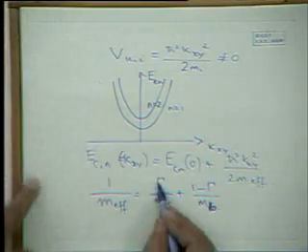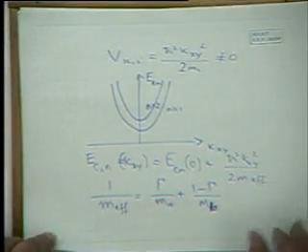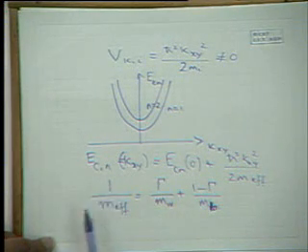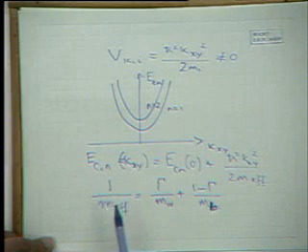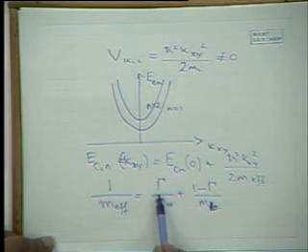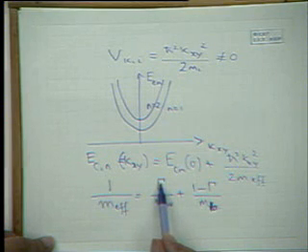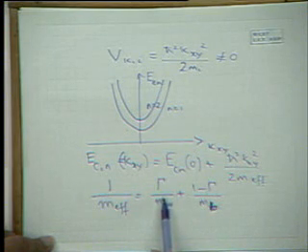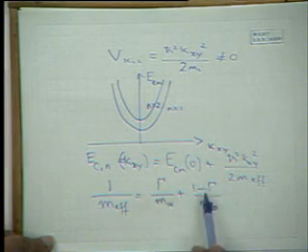So what is this gamma? Gamma is a confinement factor. Again, it's somewhat like an electron in a waveguide. When electromagnetic waves propagate, we have a confinement factor. Confinement factor is the amount of the energy of the electromagnetic wave in the central core, and 1 minus gamma is the part outside the core.